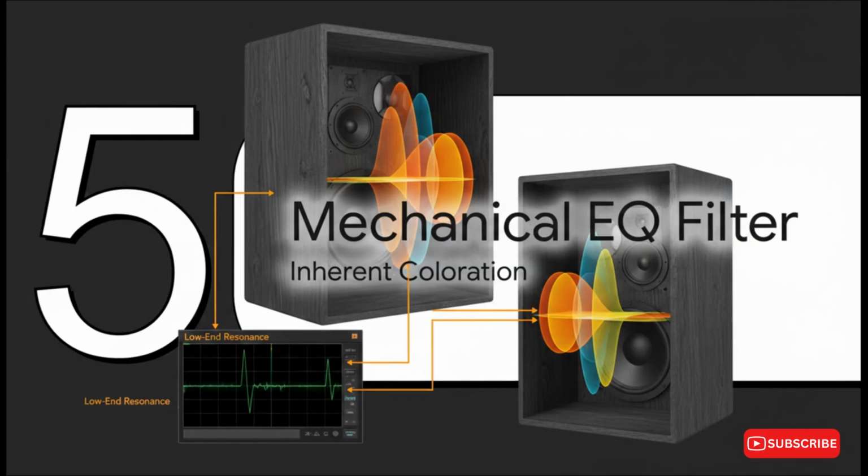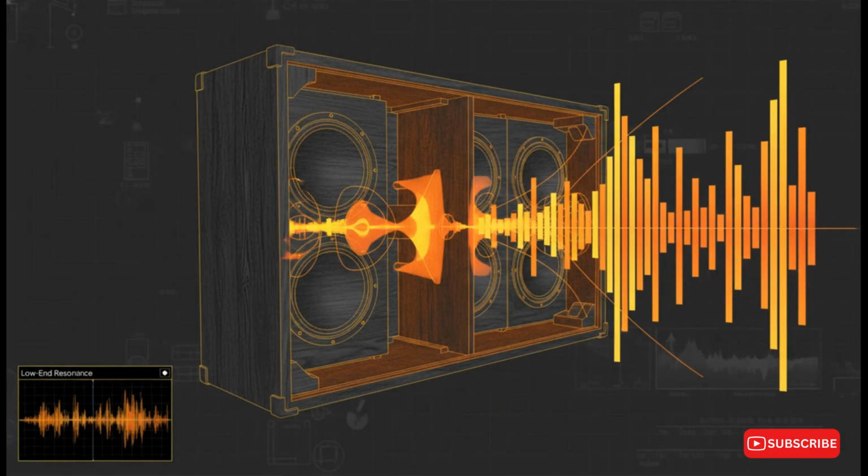And finally, Section 5, the mechanical EQ filter, the unavoidable coloration. What you really should take away from all of this is that despite our absolute best engineering efforts, a loudspeaker enclosure is never, ever truly inert. Because of finite stiffness, structural mass, and those air spring physics we've been discussing, the cabinet itself functions as a massive, permanent mechanical EQ filter. The specific wood you select, the exact internal volume, the structural bracing layout, all of it drastically alters the final frequency spectrum that actually reaches your ears. The invisible architecture is actively and unavoidably coloring the sound you experience.